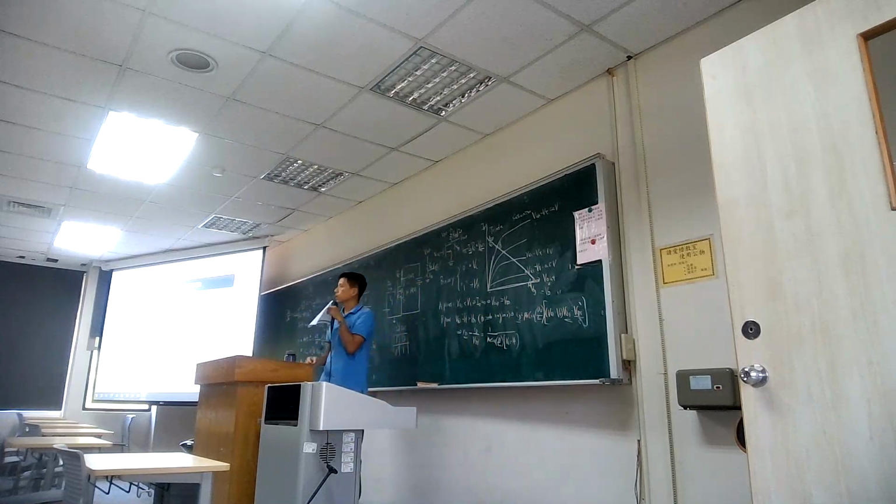And we previously assumed the current should be high, so we prefer to have a large term in the denominator. So the RDS is small in comparison with RD. So you can draw the scheme in which we get the input and output relationship as an inverter.